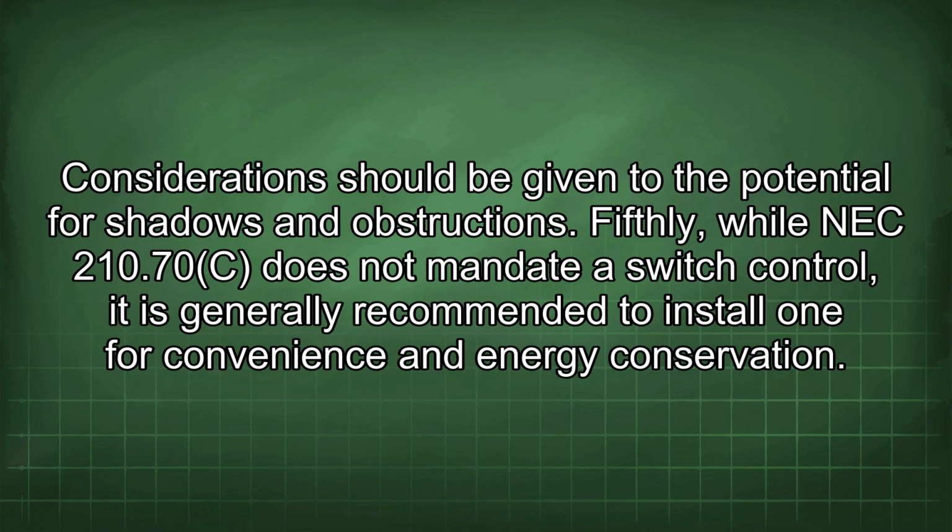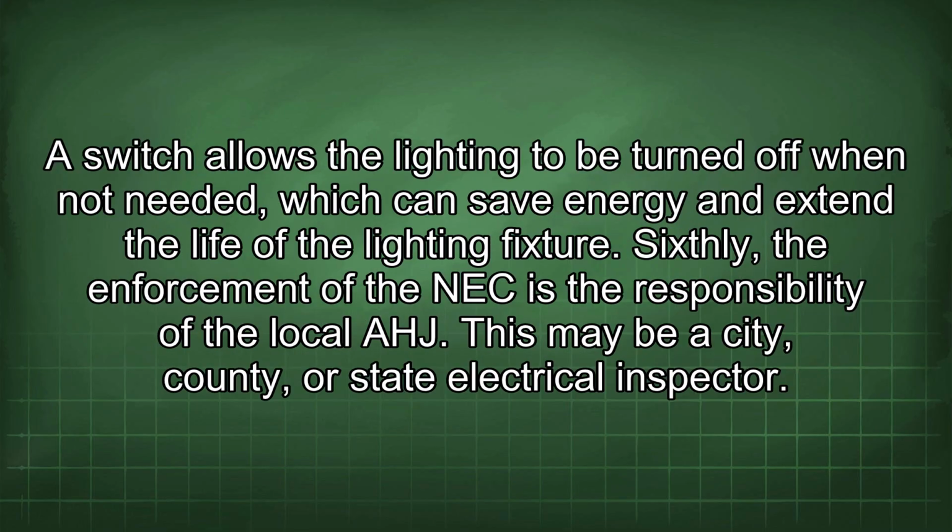Fifthly, while NEC 210.70 does not mandate a switch control, it is generally recommended to install one for convenience and energy conservation. A switch allows the lighting to be turned off when not needed, which can save energy and extend the life of the lighting fixture.